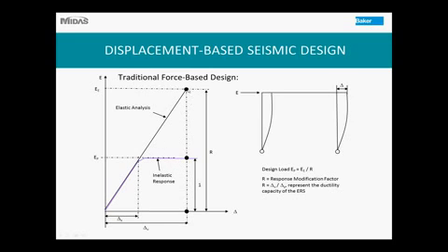And the logic behind this is that, as you see in this figure here, we've got a delta and an earthquake force, the inelastic response and elastic response, and the delta y and delta u. So this angle and this angle are two similar angles. So your design load is going to be EP, and EP divided by EE is just equal to delta y divided by delta u, which is also equal to 1 divided by R. So the response modification factor R represents the ductility capacity of your earthquake resisting system. If you have a ductile system, ductile substructures, you're going to get a larger R. If you have a less ductile one, for example, a pier wall, you're going to get less R. For a multi-column bent, which is more ductile, you get a larger R.